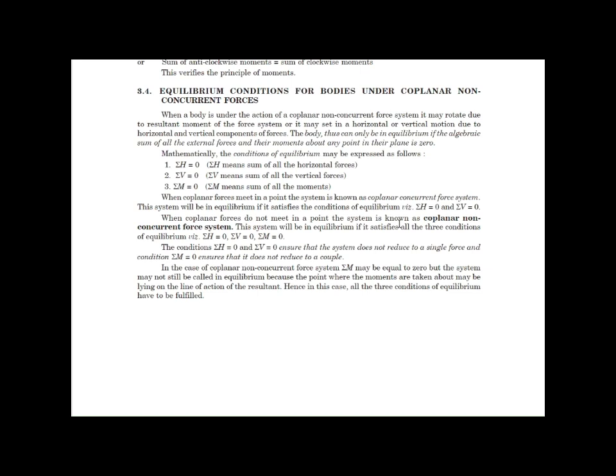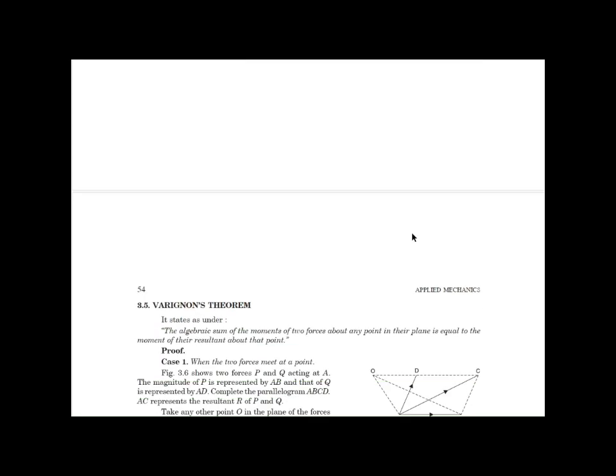If the equilibrium conditions are to be applied, that means the body is in equilibrium even after the application of these forces, then the sum of the horizontal components of the forces will be equal to zero, the sum of the vertical components of the forces will be equal to zero, and the sum of the moments will also be equal to zero. So these conditions will be applicable in case of equilibrium.